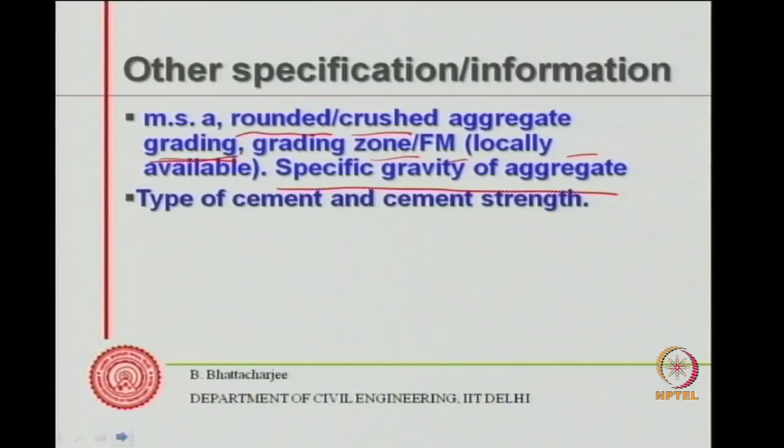We'd like to know the type of cement, and cement strength is not a necessity these days. This is not a necessity, but some of the codes might use cement strength as an input to mix design.